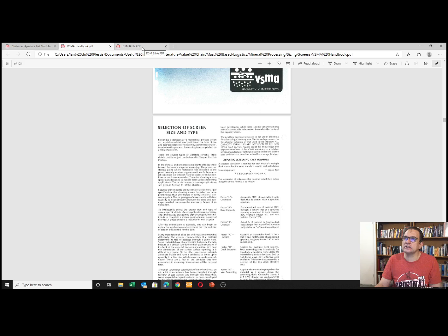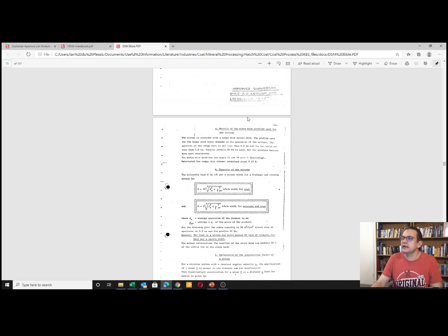Then the other one, especially for drain and rinse screens and desliming screens, is dependent on drainage and things like that. Now, the good old DMS manual, and many of you may not know this, is also from about the 1950s. This manual was developed by Stanley Carbon to develop the dense medium cyclone technology, and it's got general application in industry, in the coal industry, iron ore industry. I think even the new lithium industry is using it to some extent. So it really has wide application, and okay, it was developed in the 1950s, but it gives you a very good base to design a DMS plant.